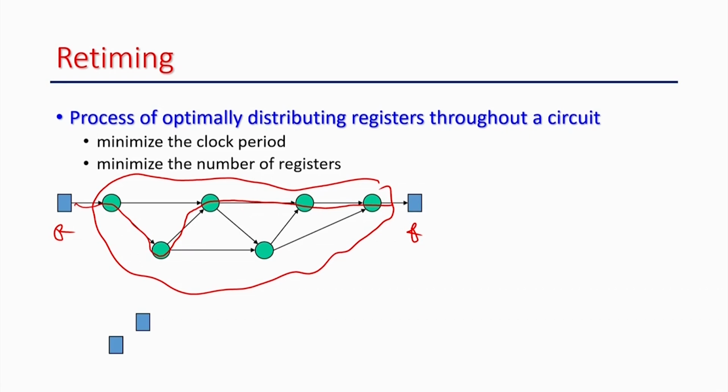And what we can do here, by retiming, is move these registers inside the circuit, right. Suppose I want to move this register from here, inside. When you move it inside, it has to be placed on all the fan outs, so it will be placed here and here, okay. Even then, it just reduces the delay by 1, right. So, now we still have 4, because I just moved it by 1. So, I can move this register again, further inside the circuit.